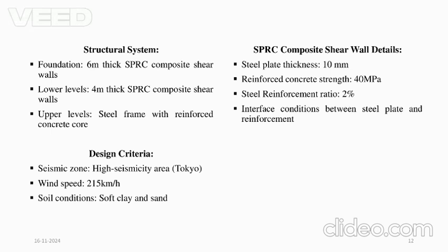Tokyo Skytree's design includes 10 mm steel plates, 40 megapascal reinforced concrete, and 2% steel reinforcement ratio, and bonded interface conditions between steel and concrete. Continuing to the test and results.